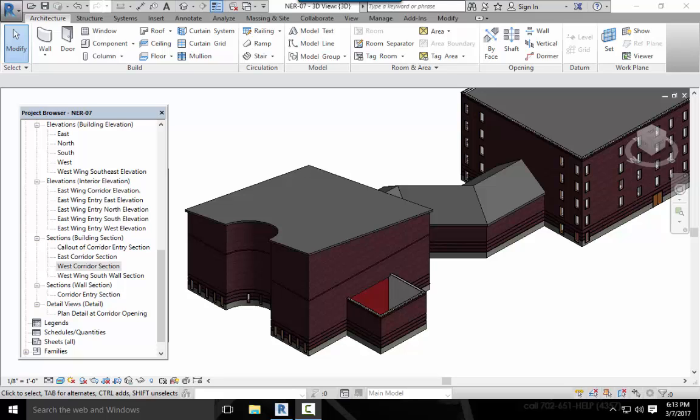Alright, creating roofs by extrusion. This essentially lets us define a roof by creating a profile. Creating a roof by extrusion is almost always done in an elevation or section view. The concept is to create unique geometry that can't be accomplished by simply using a footprint and plan. A barrel vault or an eyebrow dormer comes to mind. But there are literally thousands of combinations that will influence how your roofs will be designed.